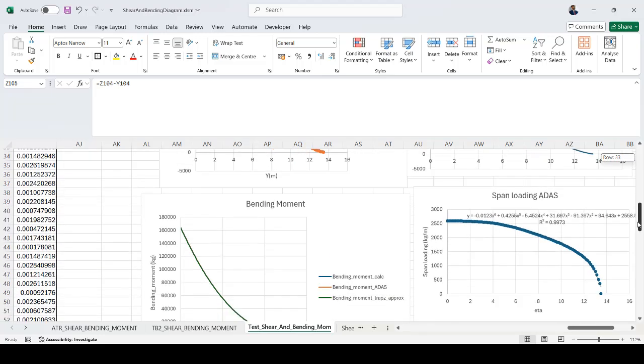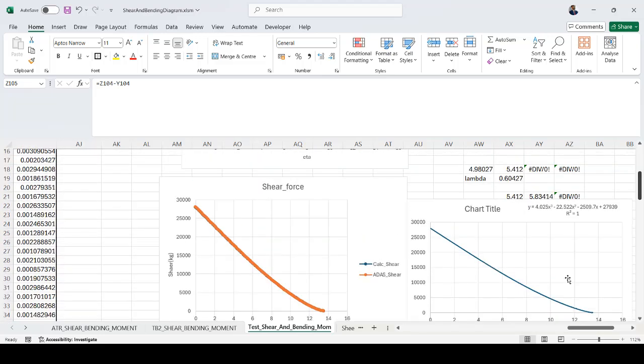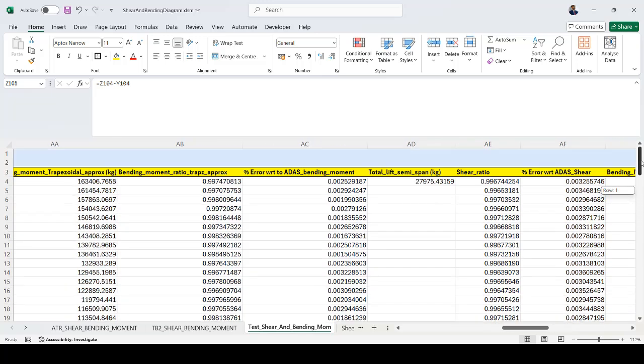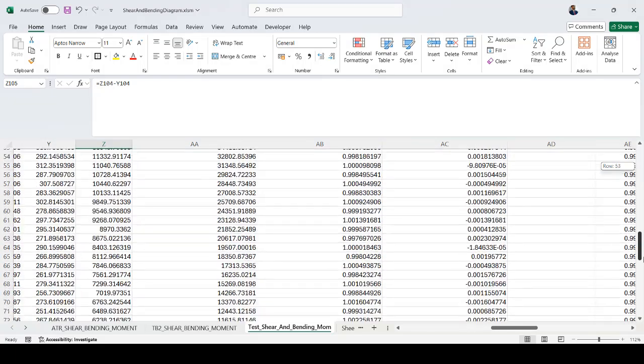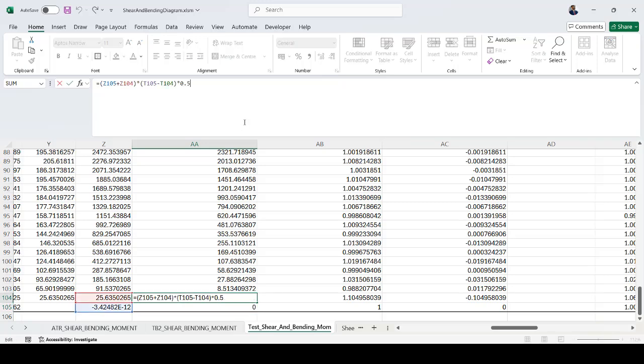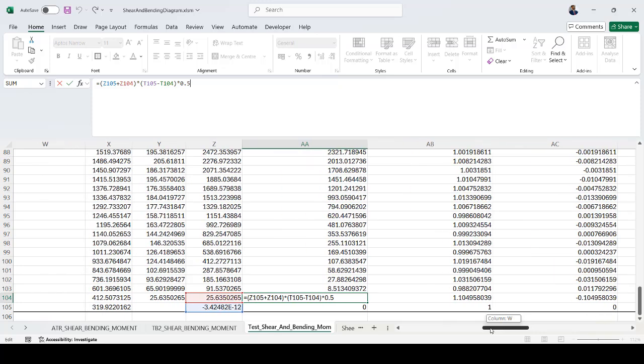So the bending moment, here the distribution is also calculated as a trapezoidal approximation, and we start from the bottom, so in this case from point B. In point B we have 0, because the load there is 0. Here it is calculated with the trapezoidal approximation, but what are the members in this formula?